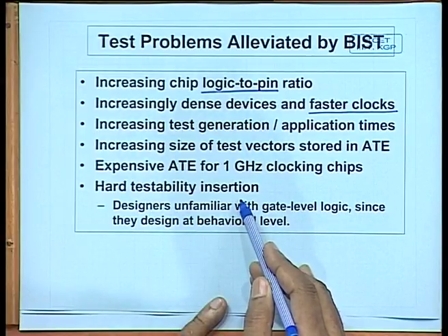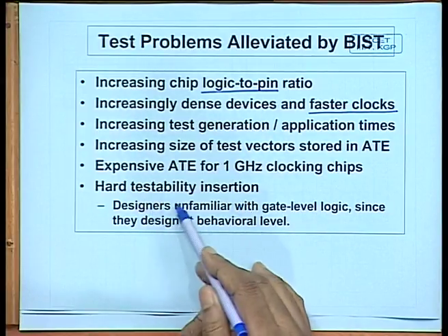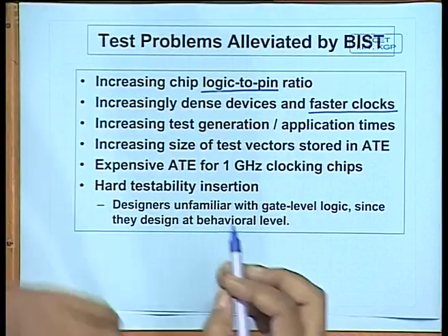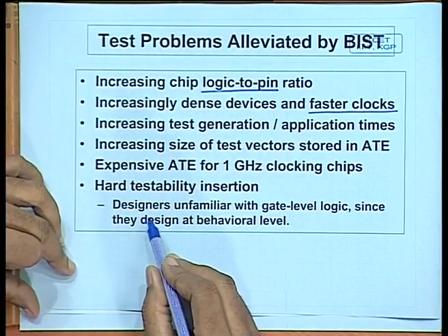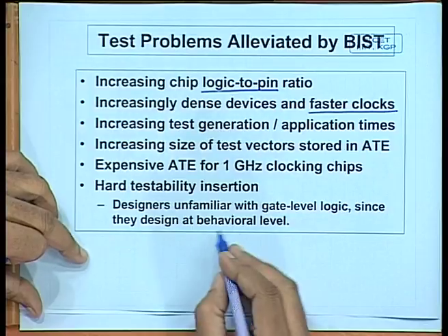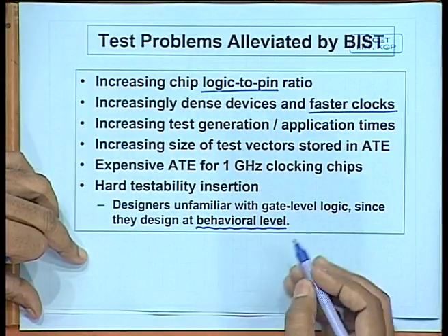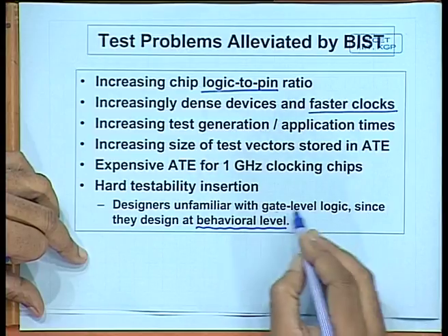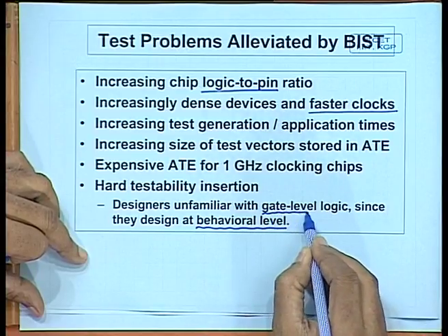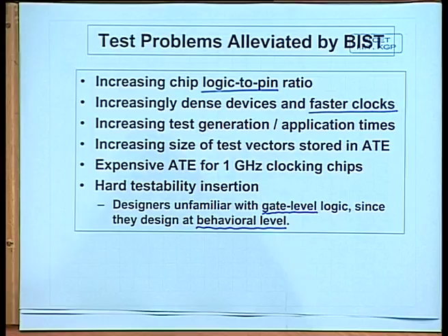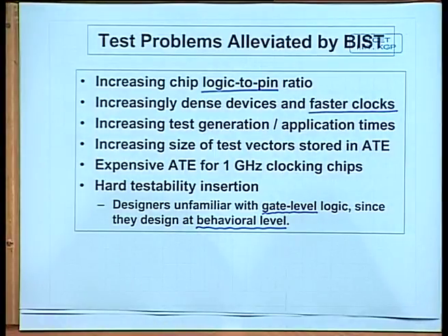Testability insertion with respect to DFT is not always very easy, because designers normally work at the behavioral level. The CAD tools automatically translate the behavioral level into gate level. So, when we talk about inserting testability features at the gate level implementation, it becomes a problem.